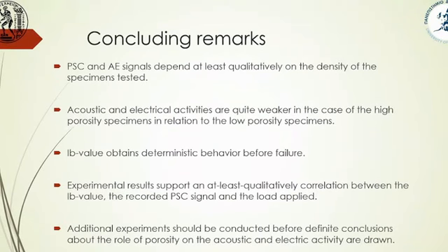Concluding remarks: we've seen that both the PSC and the acoustic emissions depend, at least quantitatively, on the density of the specimens tested. Both acoustic and electrical activities are quite weak in the case of the high porosity specimens in relation to the low porosity specimens.